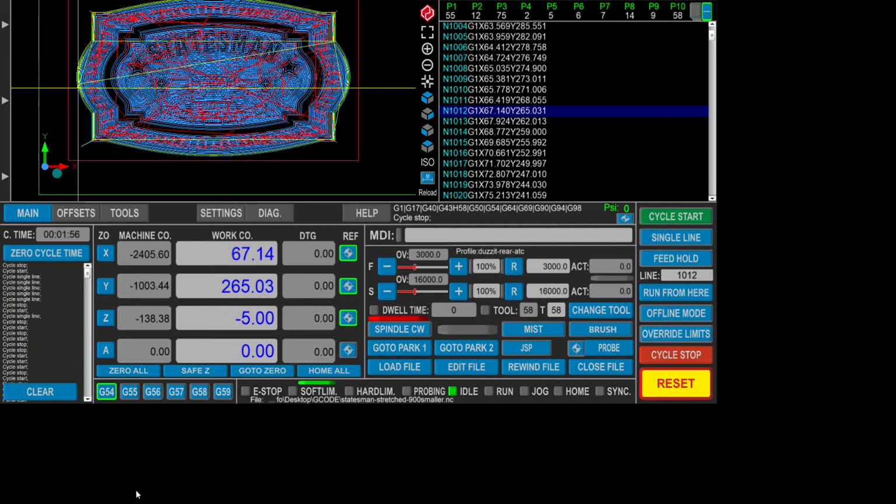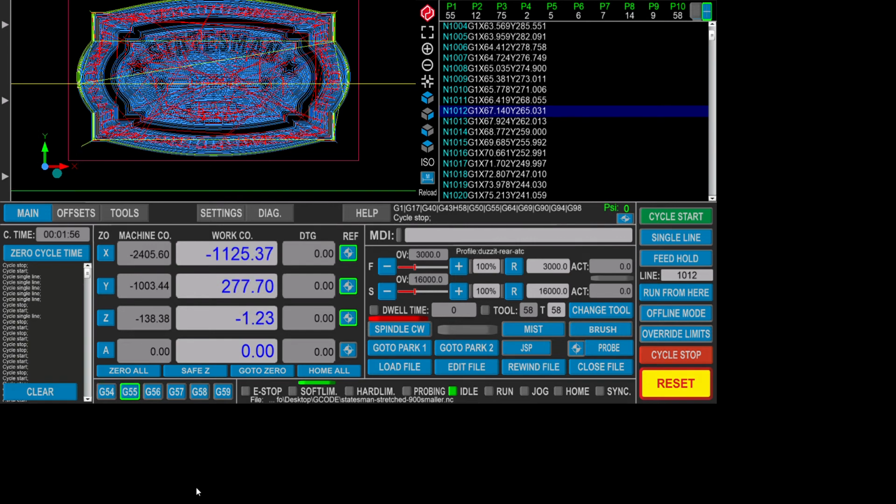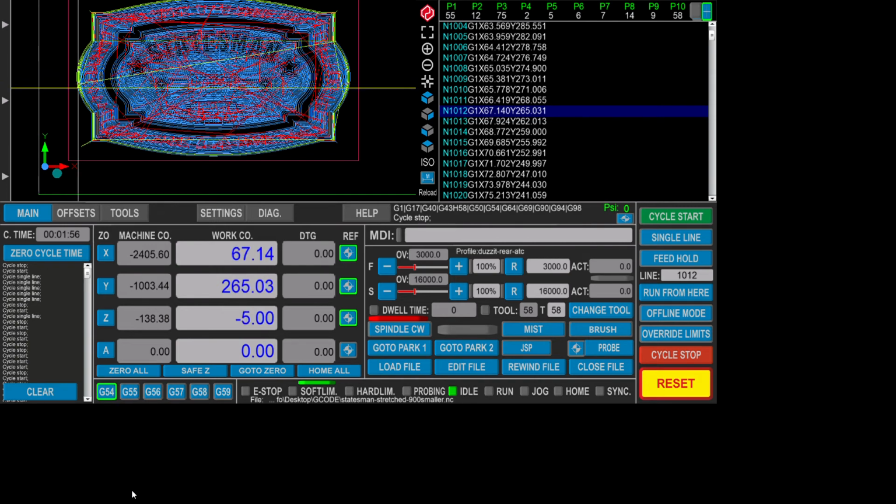Now that allows you to set the origin once. Once you've set the Z 0 for your work, you're ready to go. The other fixtures like 55, 56, 57, these can be on the board for jigs, fixed position jigs, vices, etc., whatever you need to bolt down to do your work, and it saves you from having to reset this one all the time. Now some manufacturers only allow you to use G54. We allow you another 5 spare fixtures.